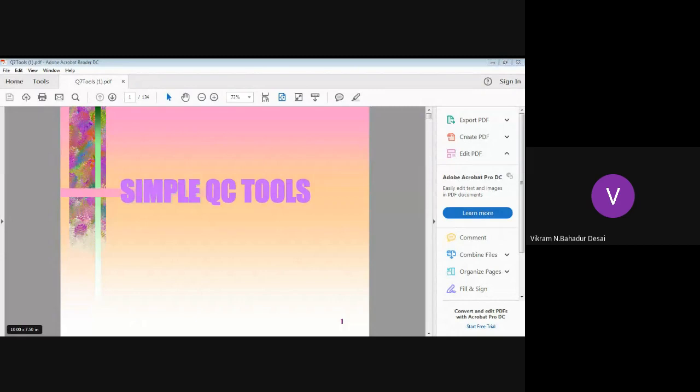Thank you. So quality control means the product is already produced, then you are going to inspect. That is called quality control. Quality assurance means you are going to design your processes such that your processes won't produce the defects themselves. So it's prevention over inspection. We say prevention is better than cure. So you need to prevent. That is why you design the process yourself.